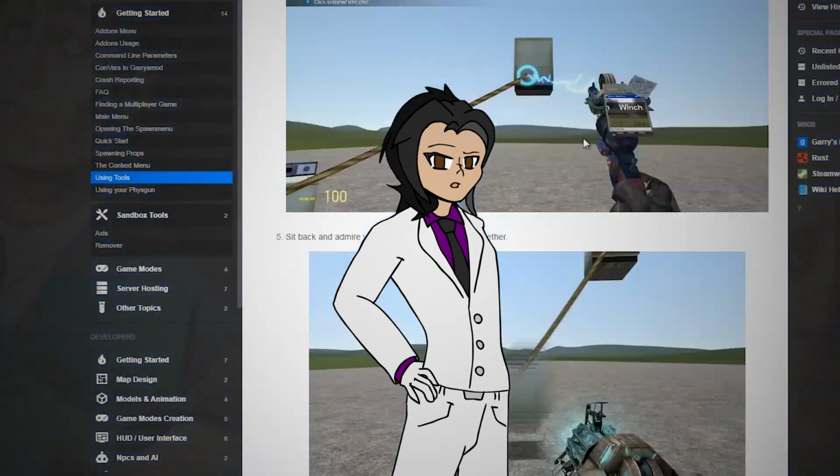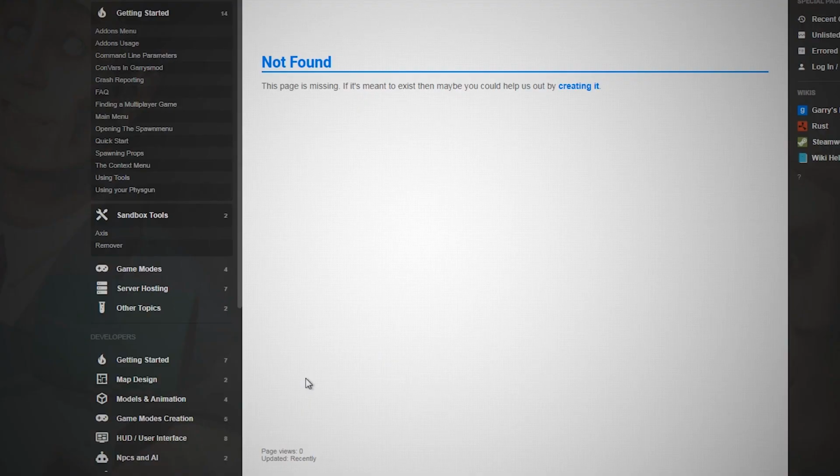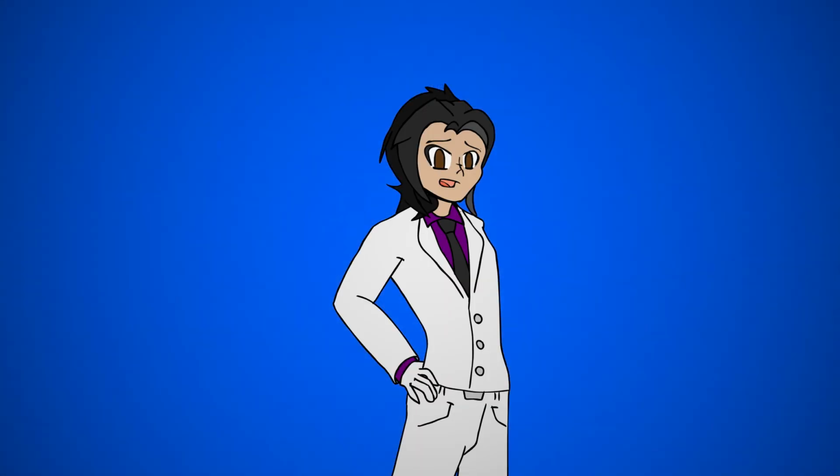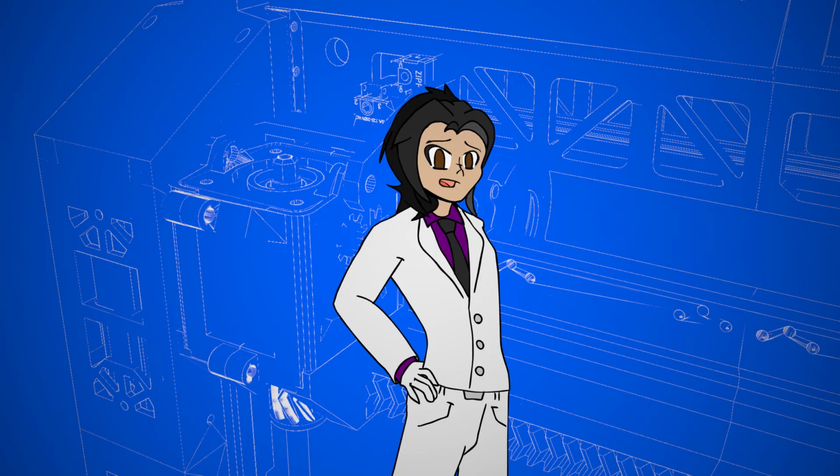Well, we still have a problem due to material science. I will be printing this printer in ABS plastic, which is not strong at all. If I were to assemble this the way that it is, it would break under its own weight. So I'm going to have to build in metal supports. Fortunately, I did find some at Lowe's. Alright, so metal supports should keep everything lined up. So I'm going to design all of this to be modular, so everything can be taken apart and put back together in smaller pieces with built-in metal supports to keep everything together.